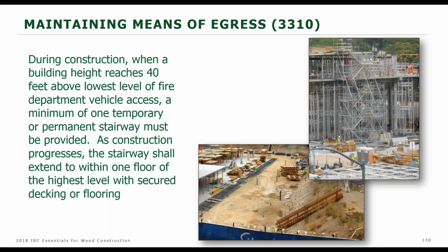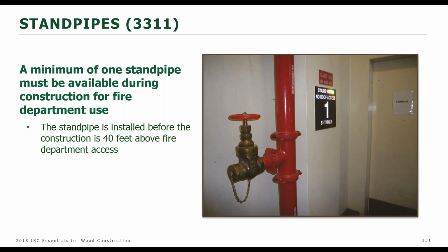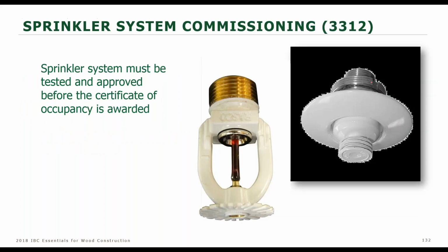This is life safety for the construction workers themselves, very important. It's in there. Construction reaches 40 feet, one permanent stairway that has to be lit, and so forth. Standpipes have to be functional when the building reaches a certain height. So if there is a construction fire, the fire service can use them. Building should never be occupied if there's a required sprinkler system that has not been commissioned and put in service. Goes without saying.